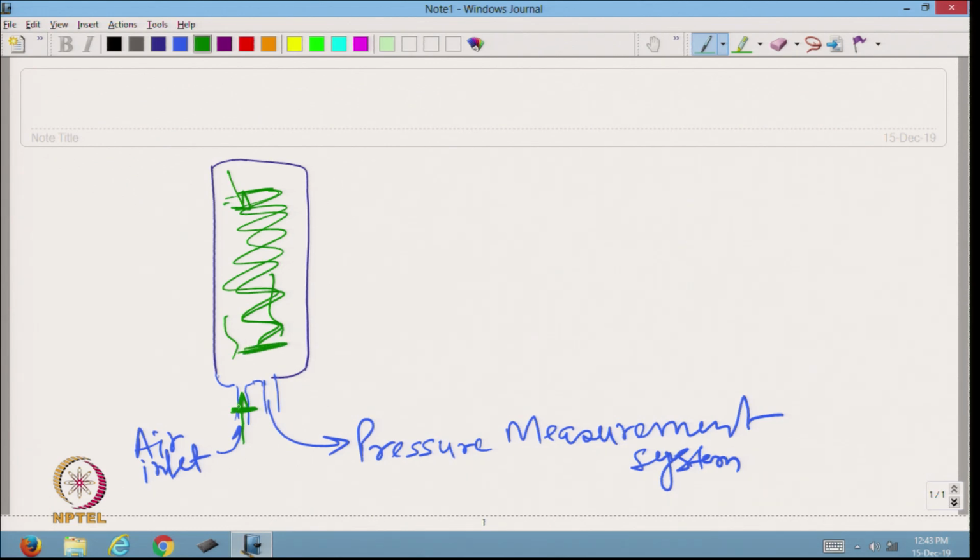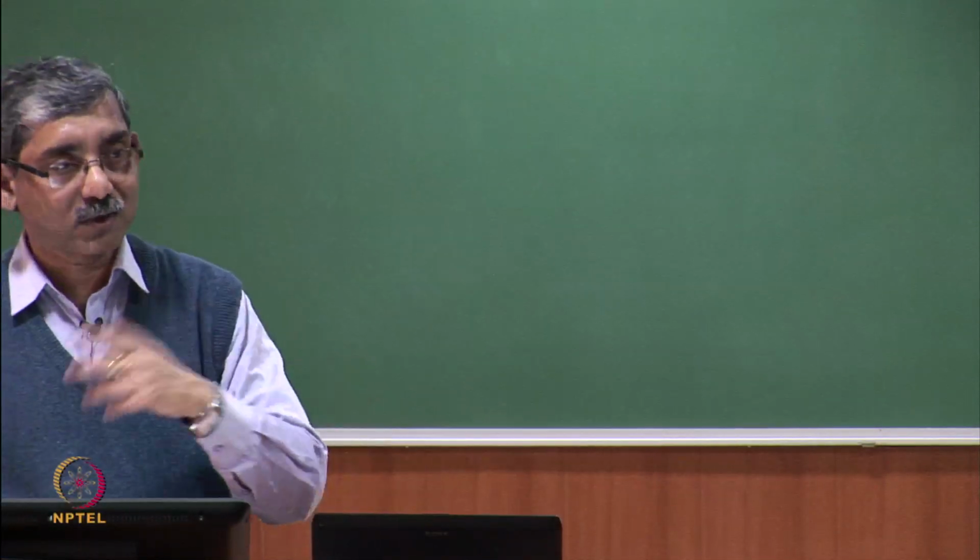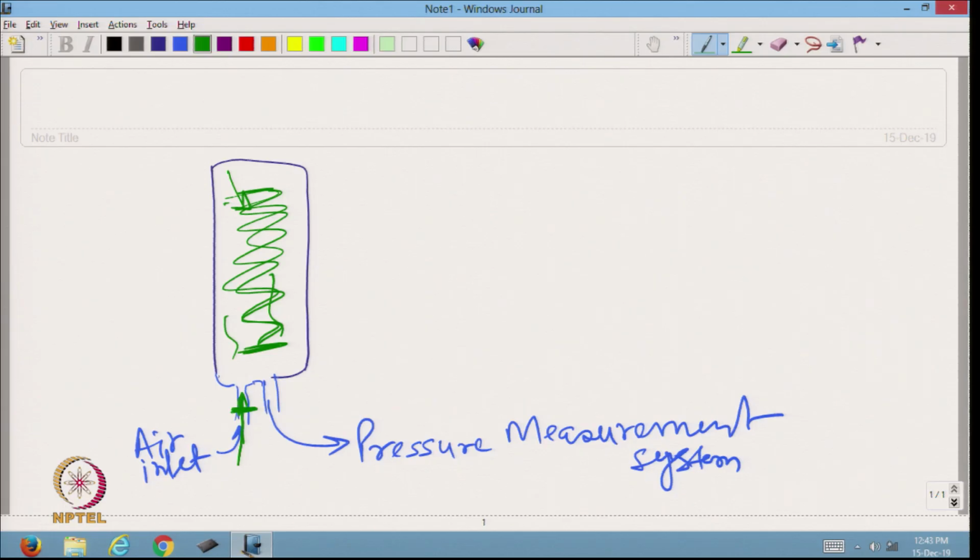Now, here the idea is to change the limb hardness, because while walking or moving, the hardness of our muscle keeps on changing. Just to simulate this, the air inlet, by using one piston and cylinder, keeps on changing. It enters when we need a higher pressure and it comes back to reduce the pressure. So, in this way the cyclic motion takes place.